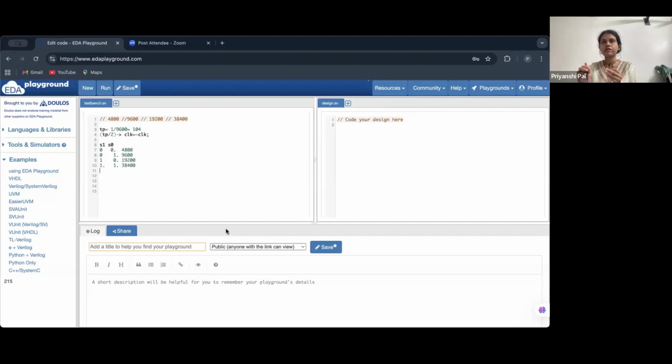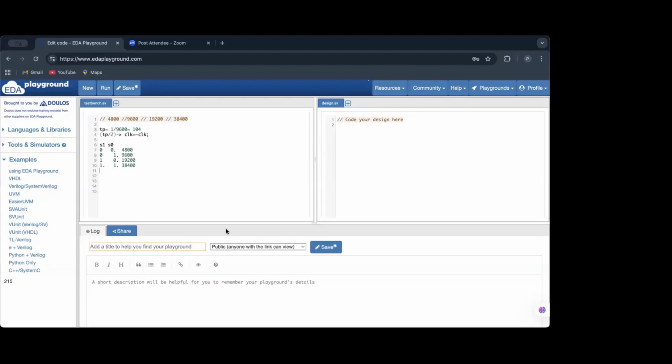From the master's perspective, if SDA is 0, then data is being sent from master to slave, and if SDA is not 0, then the data is not being sent from the master. The data is being received from the slave side, and the same from the slave's perspective. So as you said, what will happen if two masters start at the same time?